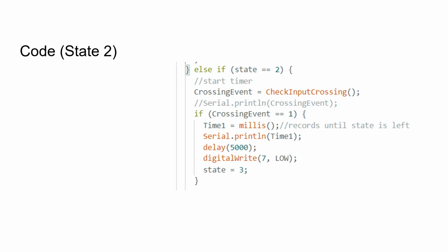At which point it starts recording time 1 and a delay of 5 seconds. For this project specifically, it would be for lifting the box off of the robot and ensuring everything is out of the way. That 5-second delay is for that. I forgot to mention, in state 1, the motor LED would turn on, signaling that the motors are off. Yes, that is inversely correlated. At this point, once it starts a timer, the motors are on, so the LED is off.